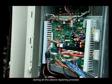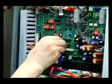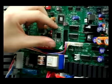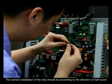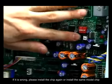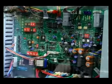During all the above repairing process, if outdoor PC board needs to be replaced, please confirm whether chips of the board have malfunction. Pins of the chip fall off, or the chips are plugged in the reverse direction. The correct installation of the chip should be according to the direction of half round. If it is wrong, please install the chip again or install the same model chip to the malfunction unit in order to check if the chip has malfunction.